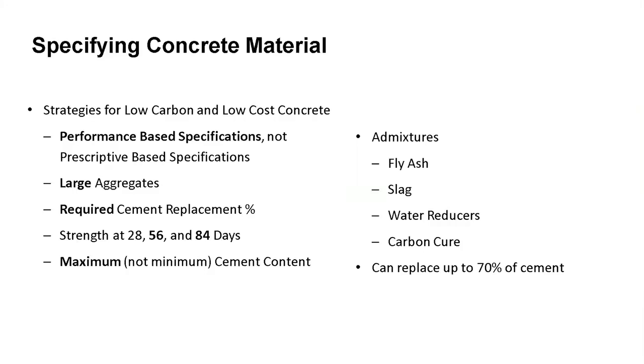So when we specify concrete, there's a handful of things that we keep in mind. I think Helen might talk about this a bit more later, but most engineers use a performance-based specification where we leave it up to the ready mix supplier to tune the mix to the project requirements. And that's more of a modern development. Historically, concrete was a prescribed mix, and I'll talk about that in the future slide.